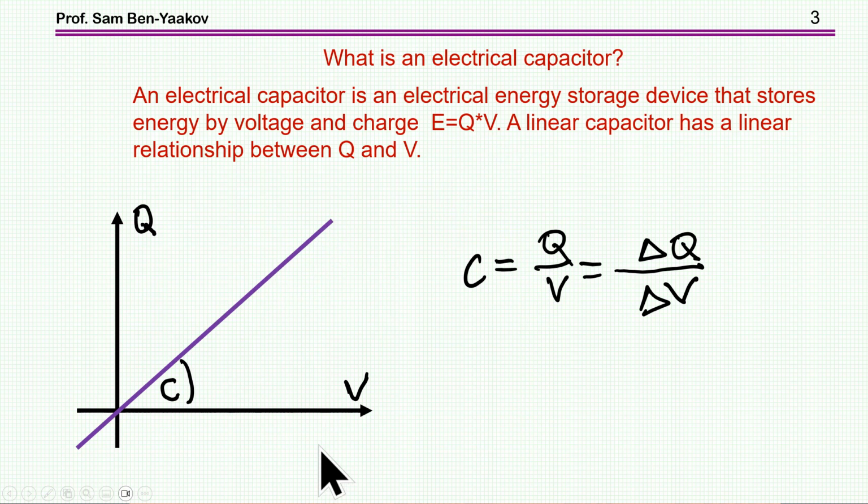This picture is very important in understanding the behavior of capacitors, linear and in particular nonlinear. In a linear case, this relationship, Q over V, this angle here, is the capacitance. But in the case of a nonlinear capacitor, this is not going to be a straight line, and the behavior is really different. But with this presentation, you can use the same tools to handle both the linear and nonlinear capacitor, because this tool gives you the basic fundamental generic relationship between the charge stored and the